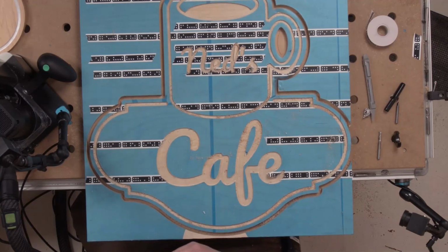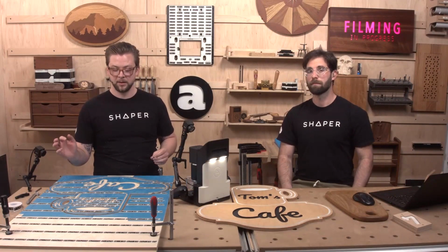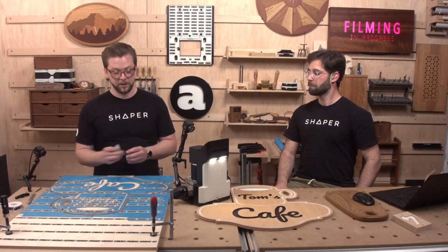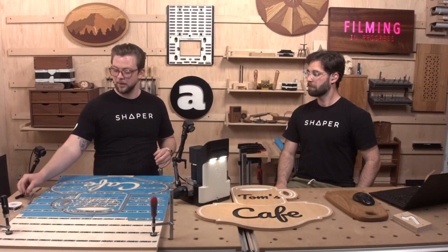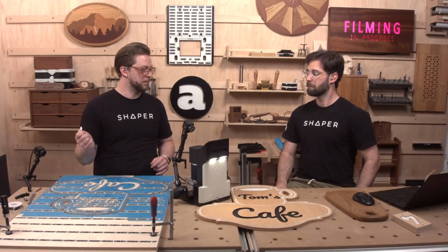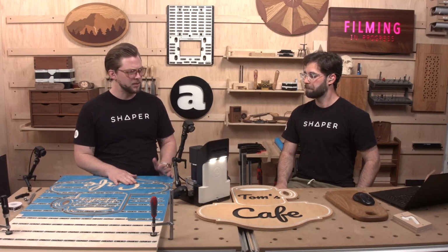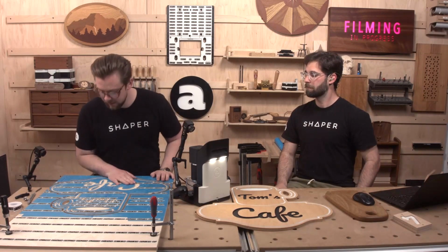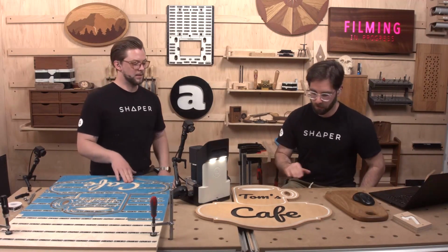I have noticed that with this Aura mask, it helps to do a light sand on your material first, so it sticks a little better. It is a pretty sticky material, but this was like rough ply. Should have hit it with some sandpaper. I've also noticed that it is sticky enough to tear some grain up on certain species, with certain plywoods especially. Not so much a worry if you're using hardwoods. But just something to be a little careful of. You can see we obviously get pretty good results with it.